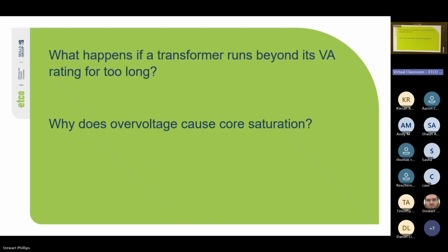So it's not about the EMF so much as about the resultant magnetic flux. If we create too much magnetic flux in the iron core after we've already saturated it, it's going to draw excess current to compensate. We're going to have more eddy currents inside the core. So if we saturate the core too much with our magnetic field, then it draws excess current.